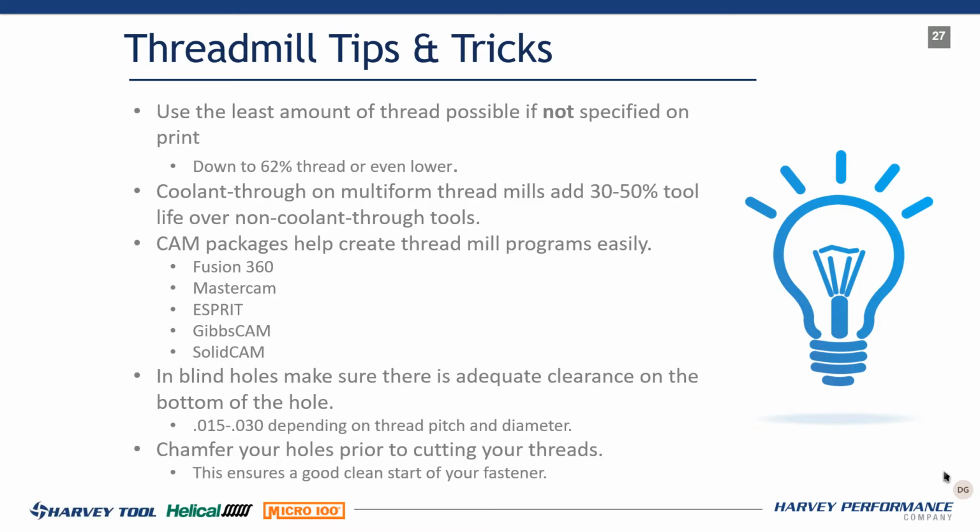Coolant through on multiform thread mills adds about 30% to the tool life. It's evacuating the chip. We actually offer coolant through thread mills in our catalog. It's something to think about, and it's something that a lot of people don't look at, but coolant through thread mills will help.